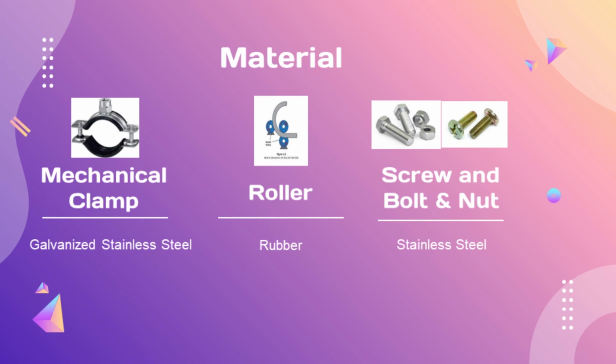We decided on rubber as the roller. Rubber rollers take advantage of the desirable properties of elastomers such as impact strength, shock absorption, abrasion resistance, high coefficient of friction, and controllable degree of hardness. Rubber is a distinct modern advantage as it is more durable than metal, which is susceptible to cracking, rusting, and other forms of damage over time. Not only is rubber more resilient, but it also handles heavy weight better as it has natural give and is flexible, which allows for even weight distribution throughout the roller instead of concentrating pressure at the point of contact.